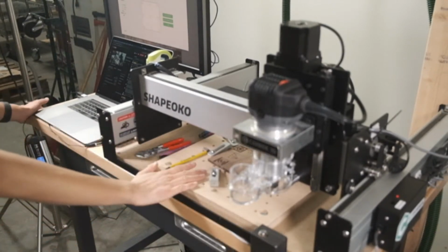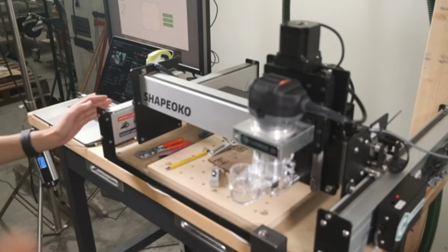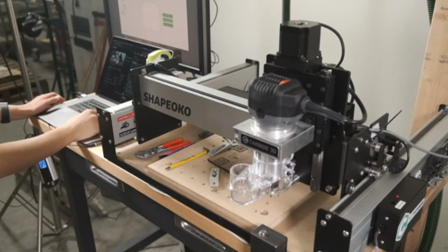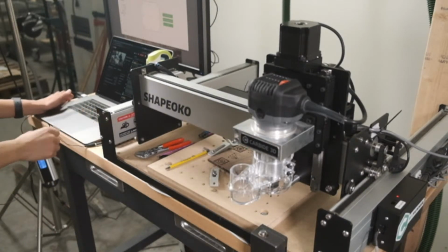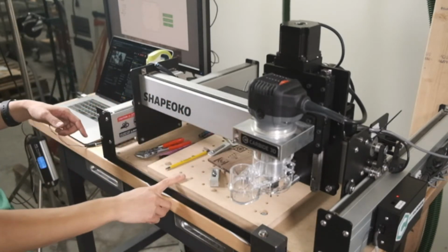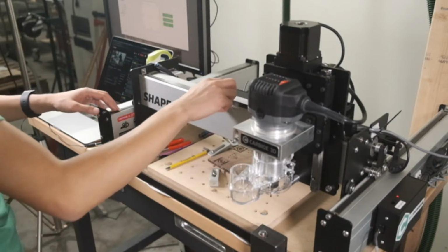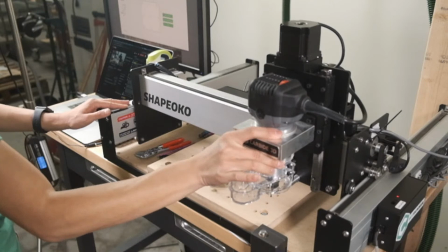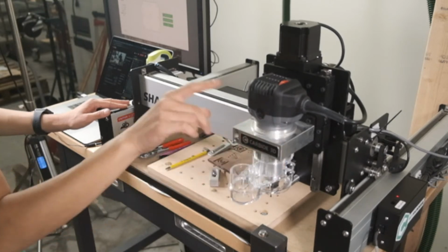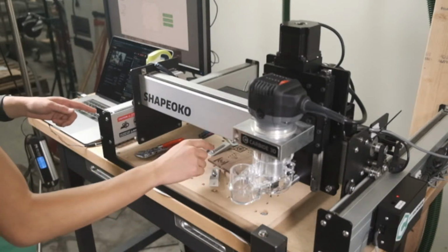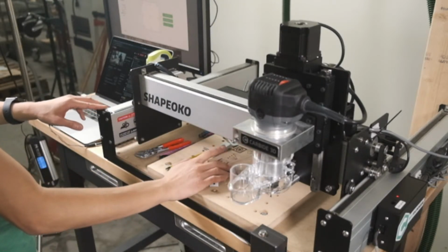checking these things. Let's see, that is focused out a little bit too far. Better. And then it's always good to just make sure everything's working before you run a project. So I'd say just go through, make sure everything's tight, just give it a little tap. Make sure there's no wobble in your spindle. There is in mine because I'm about to go over some of the causes of some misalignments in cuts.